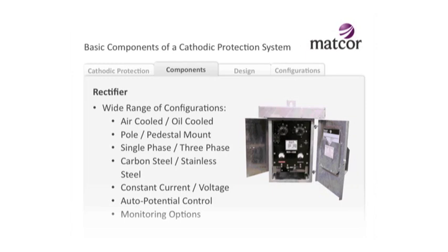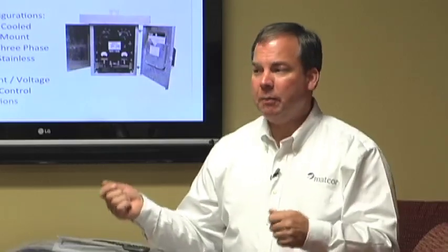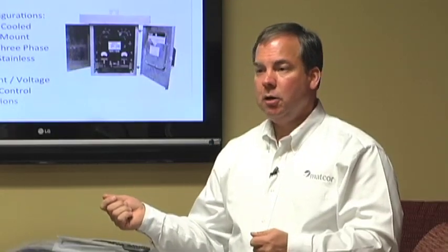Another element, especially for impressed current systems, is the power supply. Obviously, with a galvanic system we talked about, where there's no power supply, you don't have a rectifier, but this is a common rectifier. Rectifiers come in all shapes and sizes. And it doesn't have to be an AC, electricity generated power supply. Okay? Pipelines in remote areas where there's no electrical power, we can use a generator.